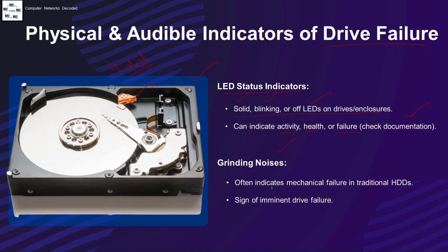And if you encounter grinding noises, this may indicate a mechanical failure in traditional HDDs, such as this one, where we have multiple mechanical parts. The noise may indicate an imminent drive failure. It means that the drive failure is imminent and you need to shut down the system and back up the data on that drive.